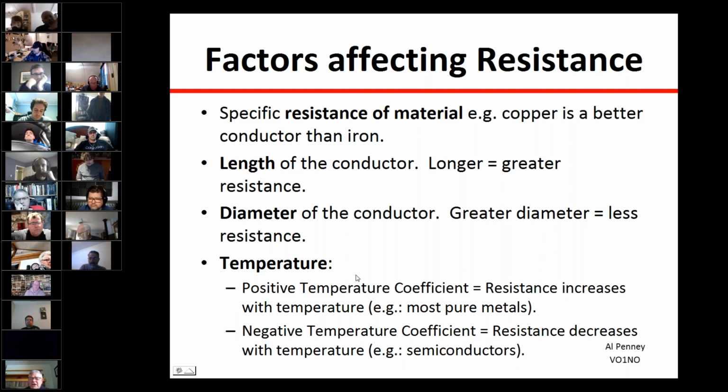Now, solid core and stranded wire, you're talking about direct current, alternating current is different. When we're talking direct current, as long as the cross-sectional area is the same, then they would have the same resistance per length. But as Diesel pointed out, solid core is just harder to work with sometimes, and it's more prone to flexing and breaking.